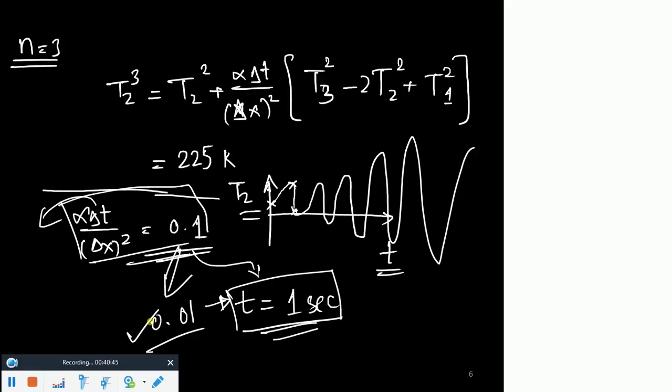Just go back and check on Google what the analytical solution for 1D heat transfer is. If you find any, compare your numerical solutions with the analytical solution. You would see that if you keep your delta T smaller, although it is stable, it is not fluctuating like this. But what do you mean by accuracy?